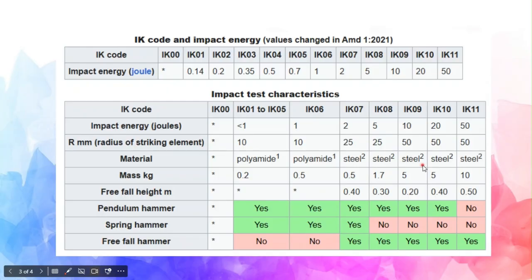As compared to them, the ductility of steel is higher, so it is prone to sustain its IK rating. What I mean to say is that if you install one FRP box in an open environment which is harsh in nature, then it will not sustain the IK impact test maybe after 2 years. But in case of steel, that will sustain. But the advantage of FRP is that it is corrosion proof.